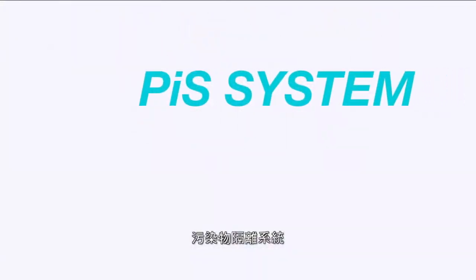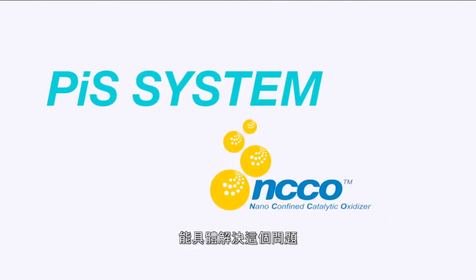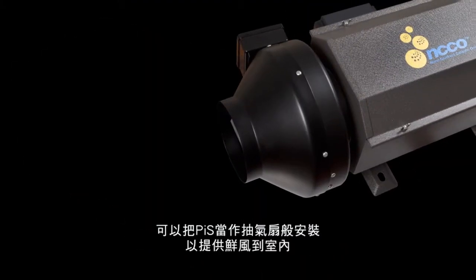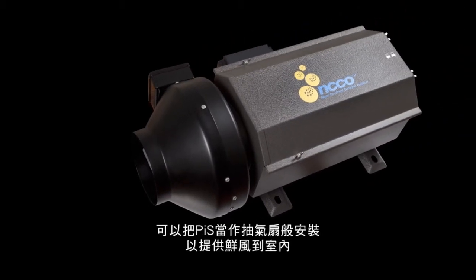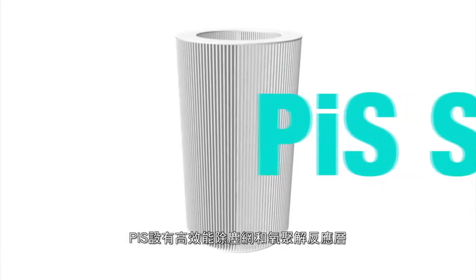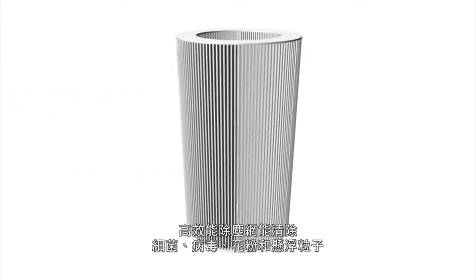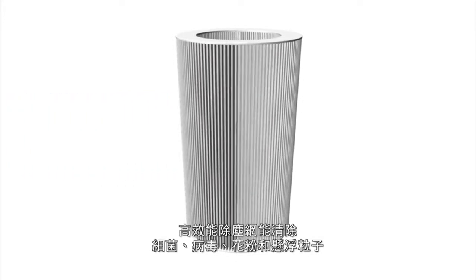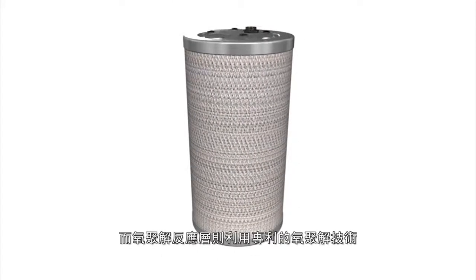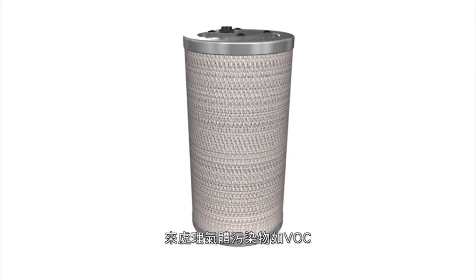Our pollutants isolation system, or PiS for short, provides a concrete solution for this situation. To create a clean room in a polluted area, PiS can be simply installed as a ventilation fan for supplying fresh air to the room. PiS is equipped with a dust filter and an NCCO reactor. The dust filter can remove bacteria, viruses, pollens and suspended particulates, while the NCCO reactor, using the NCCO technology, can deal with gaseous pollutants such as VOCs.